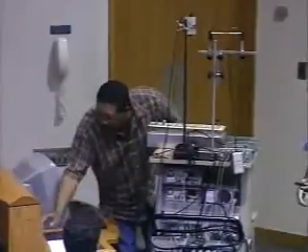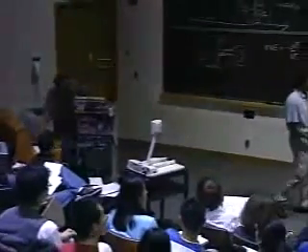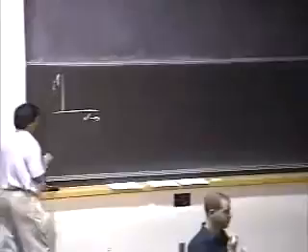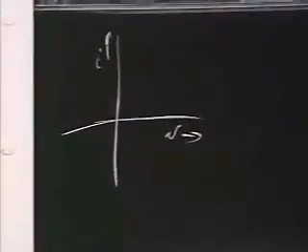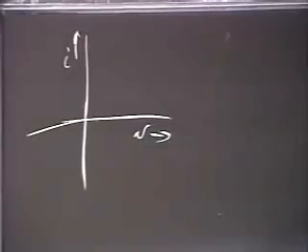I'm going to switch to the other. Okay, so what you see out here, we characterize lumped elements by their VI characteristics. We apply a voltage, measure the current. So what I can do is plot I here and V here and see what it looks like. I can characterize elements by their VI relationship, and there are a bunch of elements that I can create based on the VI relationship.